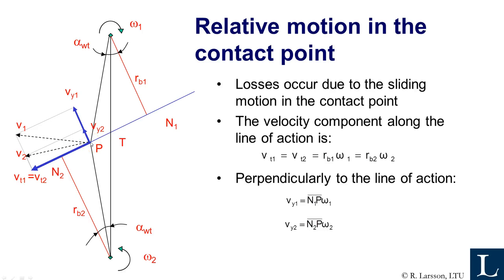And starting then with the first, getting the velocity components here. So we have velocity components that are normal to the gear flank, and those who are transversal to it. These are the sliding speeds. So one gear tooth is moving at this speed, and the other one at that speed. So the difference here is the actual sliding speed.